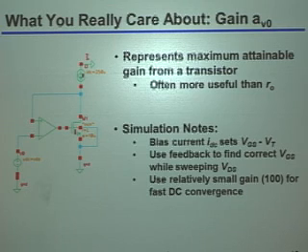Okay, so the question was, it seems like, if this gate to source voltage is changing some, that will actually change the GM that you're getting. And you are, in many ways, correct, that if I really measured the exact V star, it's probably going to change as you change the VDS. But it shouldn't change very much to the extent that the transistor is operating in a reasonable regime, right?